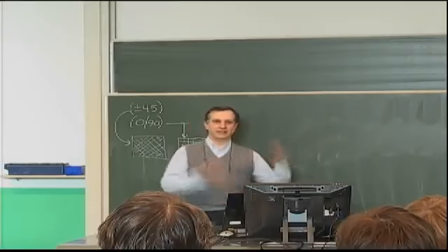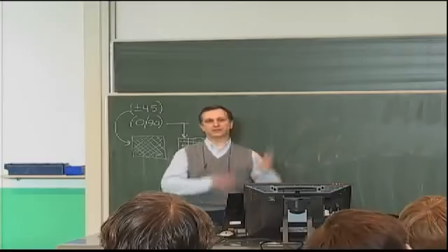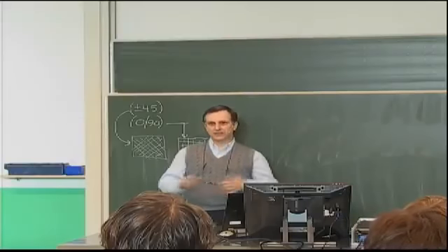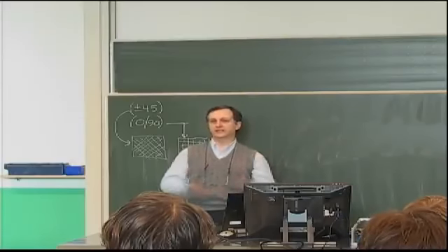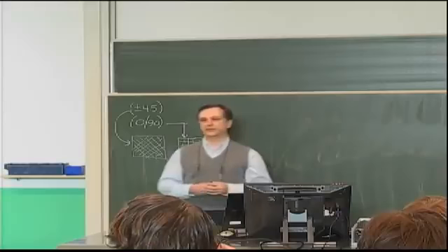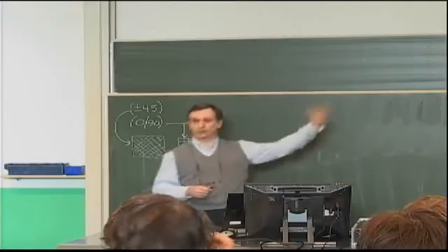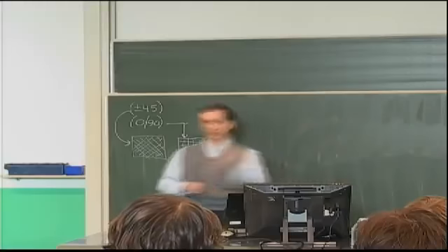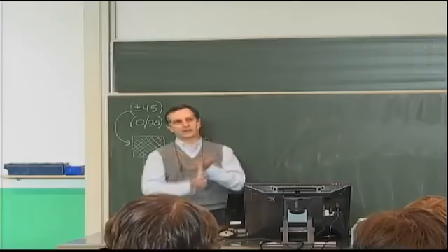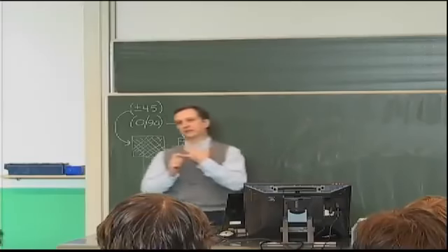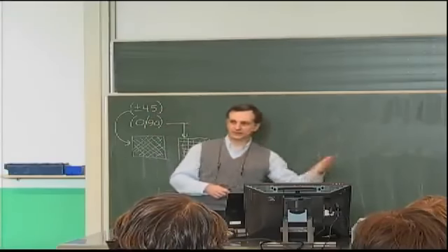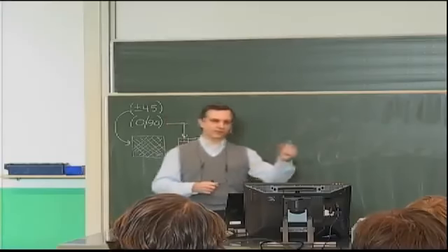And I was quite good as a student, as a master's student and undergraduate student. I had gone to a good university, so I was a bit upset and disappointed how he could just by looking say that the results were wrong. And he said, go do something and don't come back until you fix it. It took me a week and I had to go through a solution like this, which was approximate, but at least showed me, first, my boundary conditions on my finite element model were wrong. And second, the way I was applying the loads, I was presupposing the displacement pattern, which was not necessarily correct. Now, this guy was 20 years older than I am, and he could just tell by looking at it.